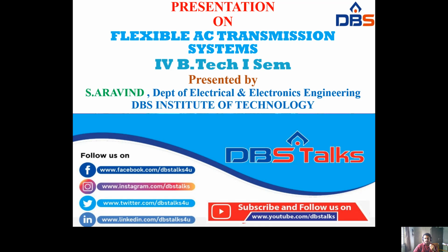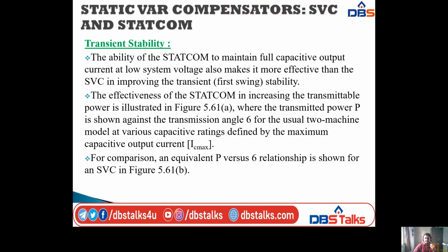The first comparison is transient stability. By using this comparison, I will explain how STATCOM differs from SVC. The ability of the STATCOM to maintain full capacitor output current at low system voltage also makes it more effective than the SVC in improving the transient stability. That is the first swing.